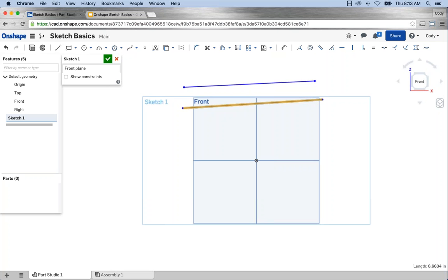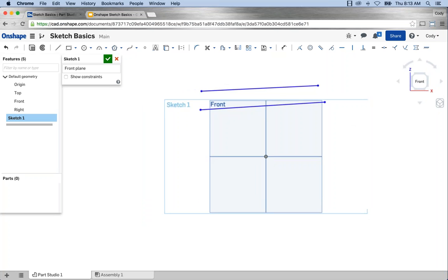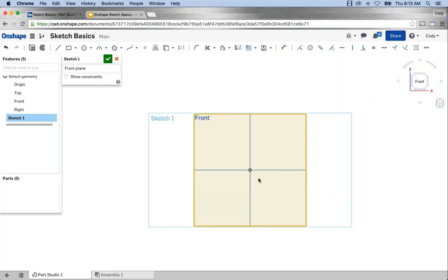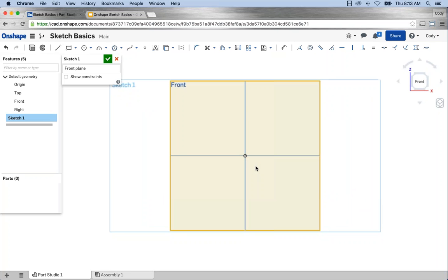That's the obvious approach. However, if you want to get rid of a whole bunch of sketch geometry at once, left-clicking individual sketch entities is not ideal. You can window select, and that's a left-click drag over the geometry. So you can window select and delete sketch geometry that way as well. Just a tip, especially as you're just getting started, you will need to delete occasionally. Select the entity, hit the delete key, and it disappears. So that is the lines.